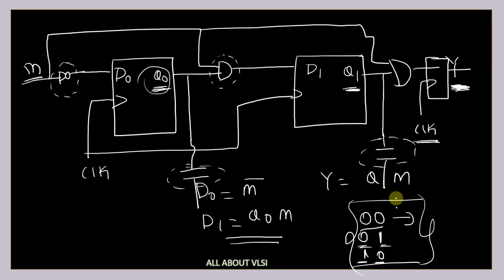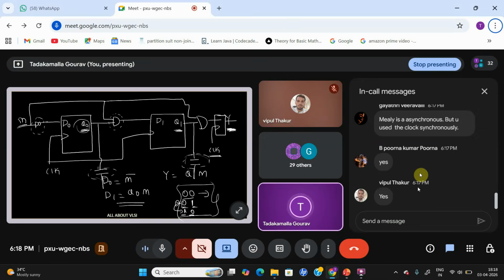And if you are going to give 0, 1, then this means you're giving high voltage over here. And next, since it is 0, that means you're going to discharge this capacitor, and you're going to again charge this capacitor because it is getting from 0 to 1. So that means you're going to charge and discharge these capacitors this many times. Am I right or wrong?